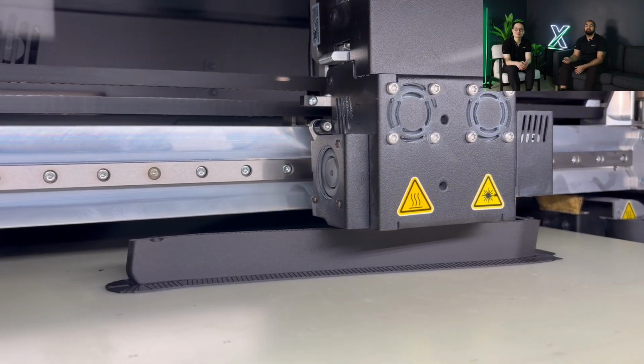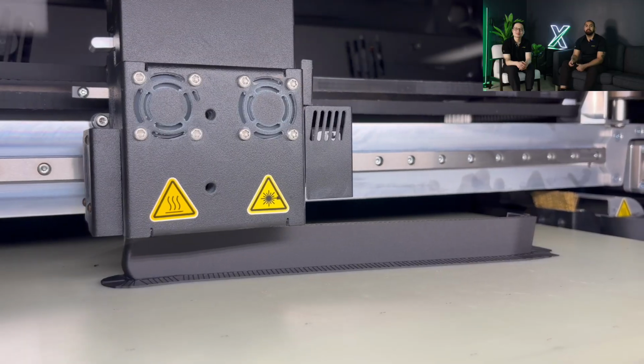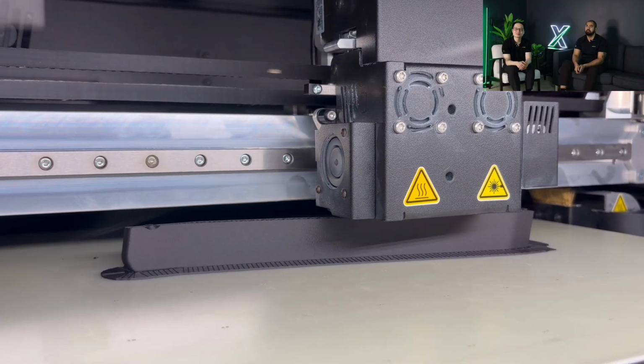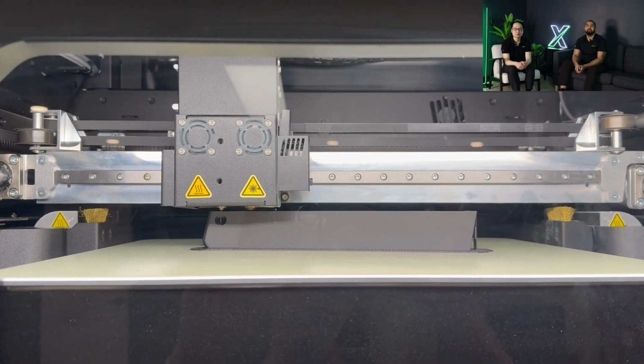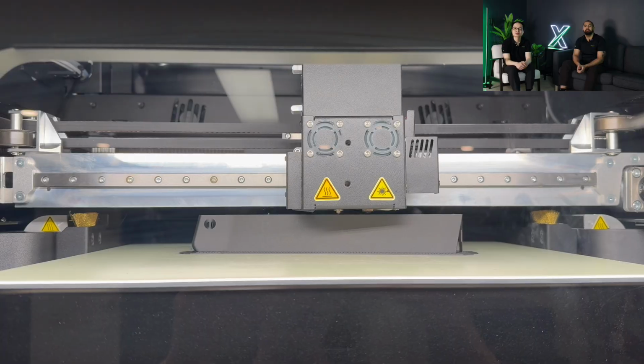So here we can see the vertical safety factor is 0.94 and a cost of 10.89. The values aren't the most important thing here. They'll mostly be used for comparison. So for example, when we place the part horizontally, we see that the safety factor increases by 56% to reach